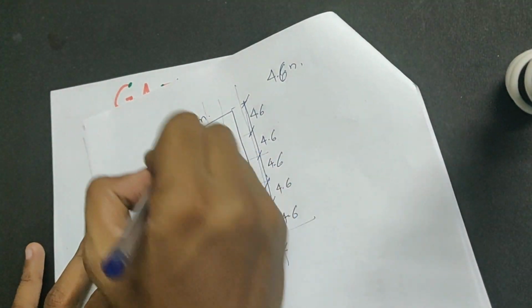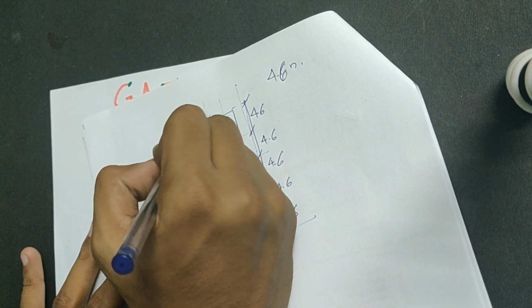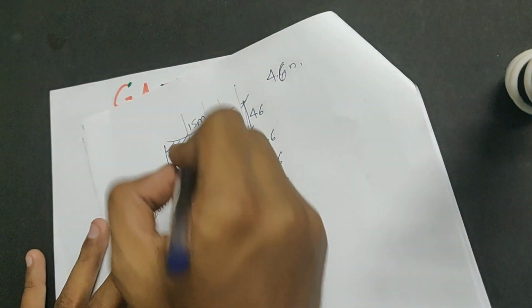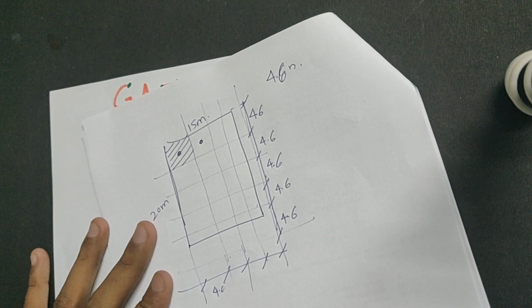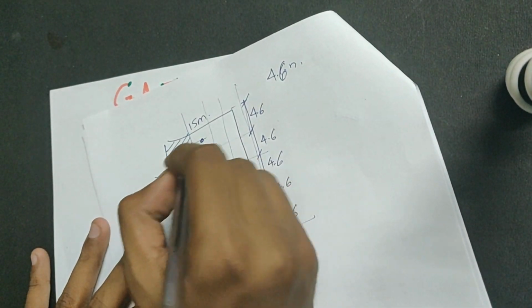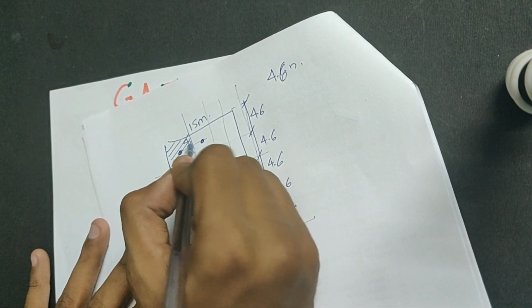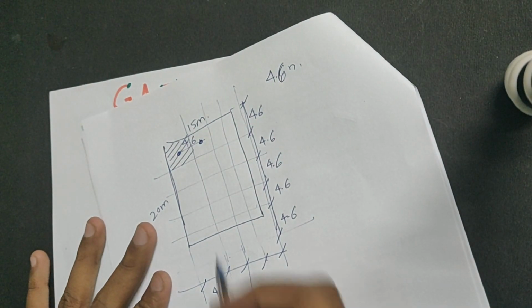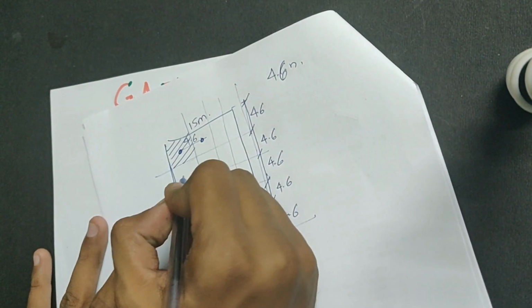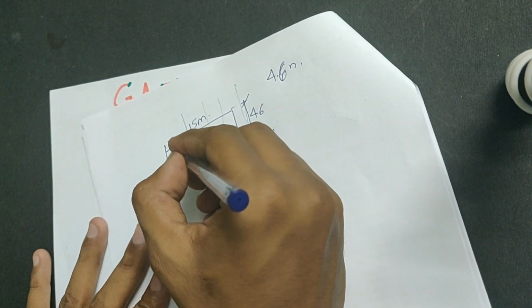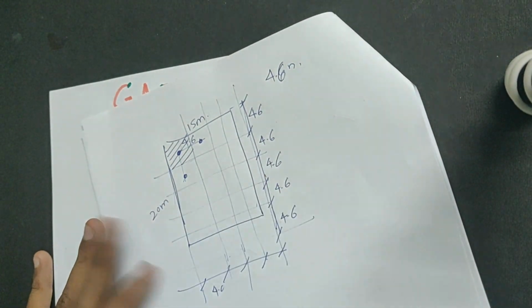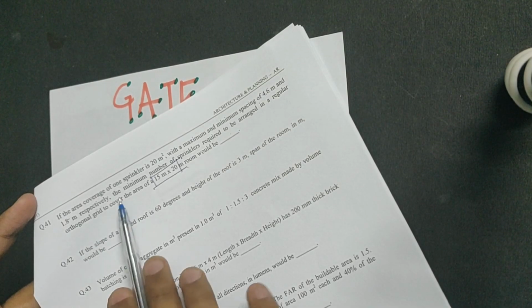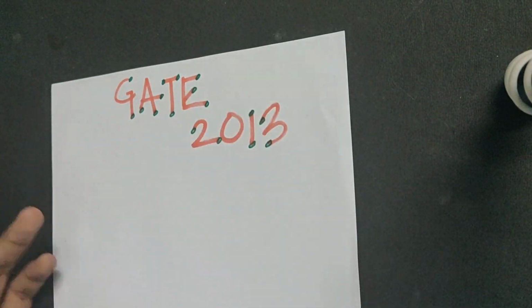So you'll place your sprinkler in between. Similarly this will also be in between, right? And the distance will again be 4.6, correct? Similarly in this grid you'll place this in between. This is again 4.6, and it is also given that the area coverage of one sprinkler is 20 meters square.